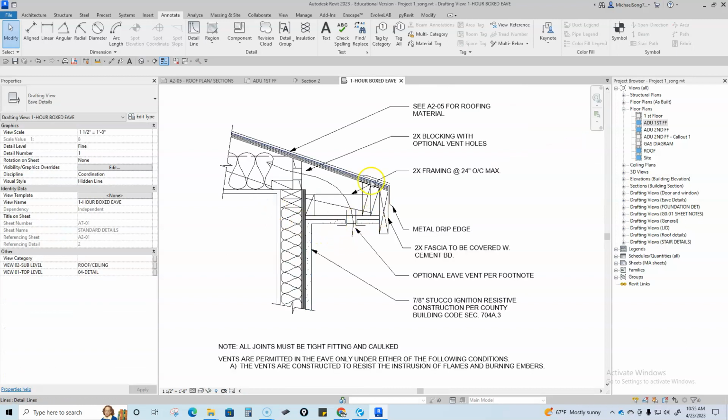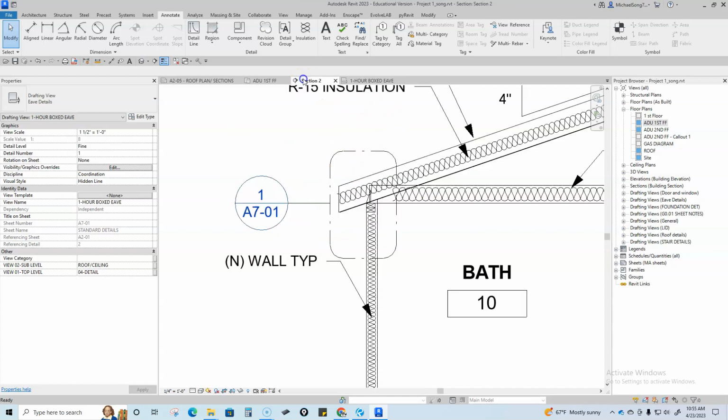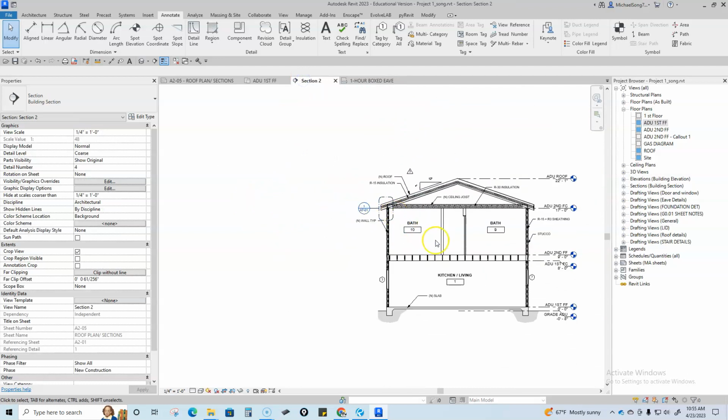That's really our standard detail for what we call a fire rated soffit, where you have your stucco that comes underneath and covers the overhang so that fire embers won't go through and get into the attic and burn the roof. So it's like a little extra fire protection that you have to do for areas that have a very high fire zone rating. And drawing such a detailed view is virtually impossible when you're looking at a drawing that big.